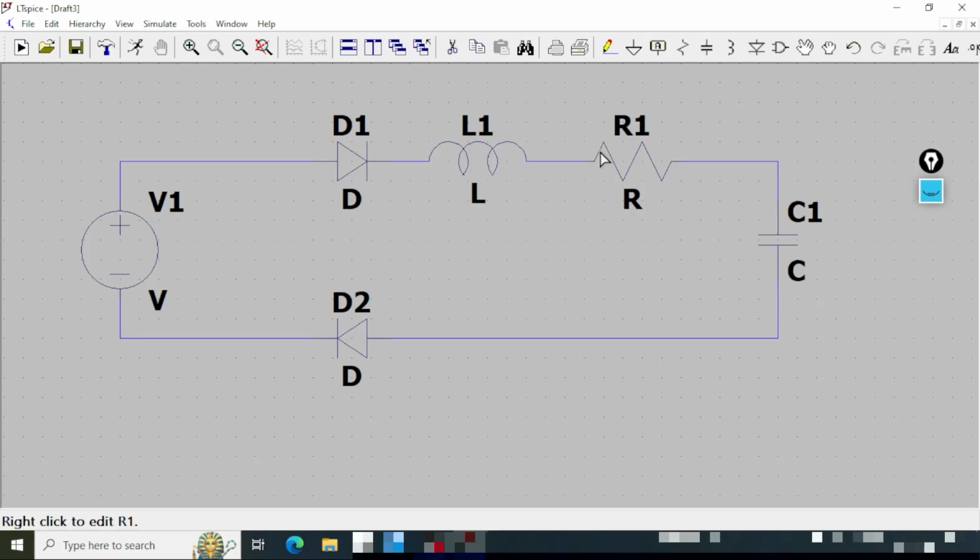Now I will place one particular ground connection. So this is the ground. I'll place a ground here. I place the ground and I don't need this, so I right click. Now I will again click the wire, come to this point, I click it, and then I move vertically upwards. My crosshair is well aligned with the line, and I click it so that the interconnection is in. Now I hit escape from the keyboard, and you can see the circuit has been drawn.